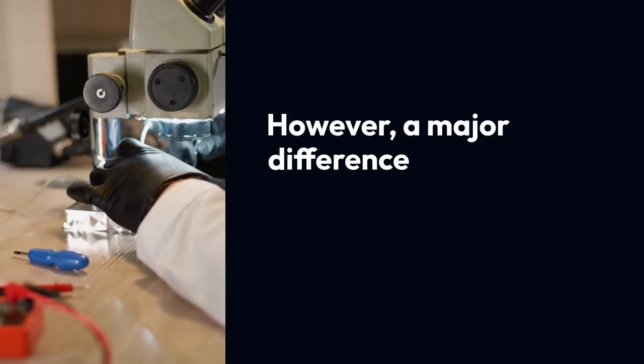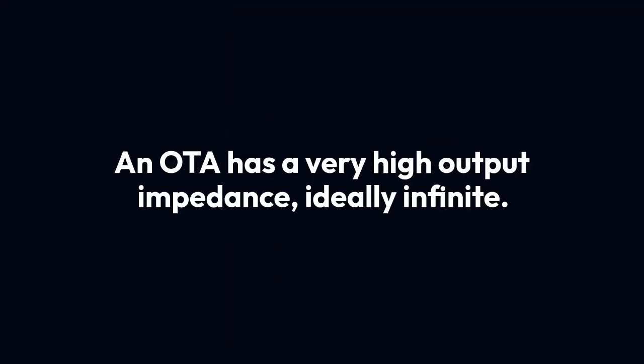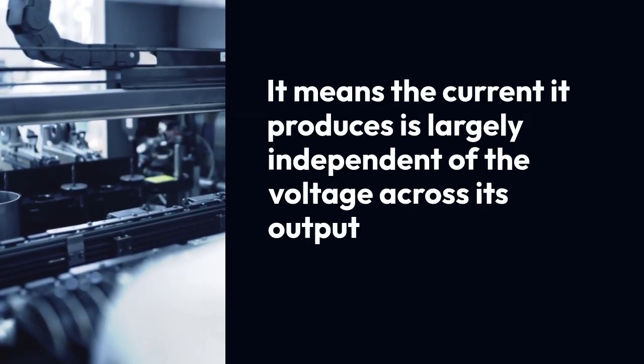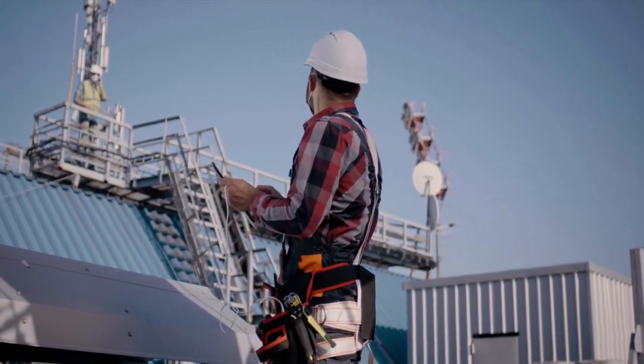However, a major difference lies in its output impedance. An OTA has a very high output impedance, ideally infinite. This high output impedance is characteristic of a current source. It means the current it produces is largely independent of the voltage across its output terminals. This is the opposite of an op-amp's low output impedance.